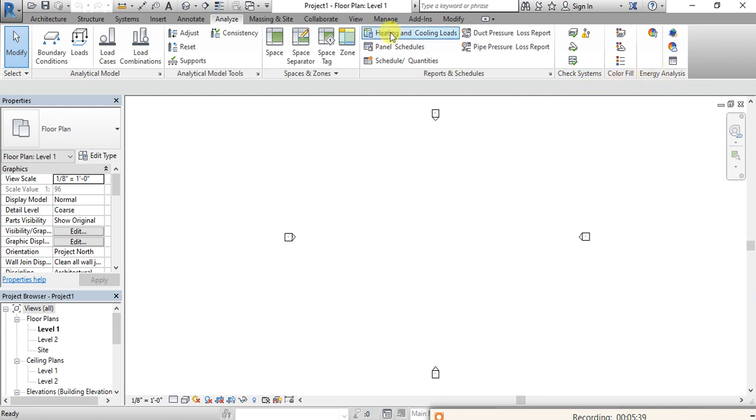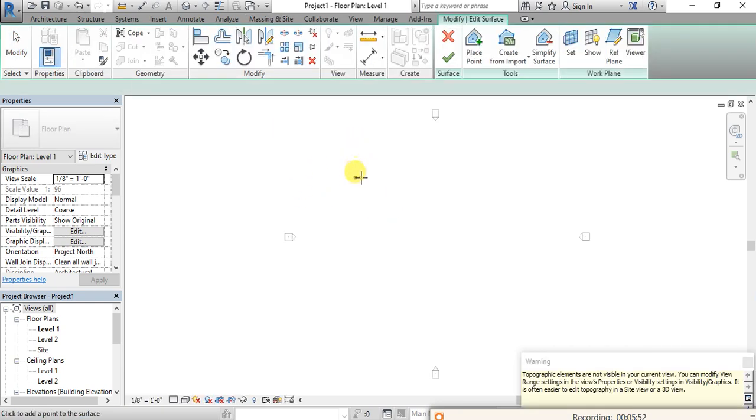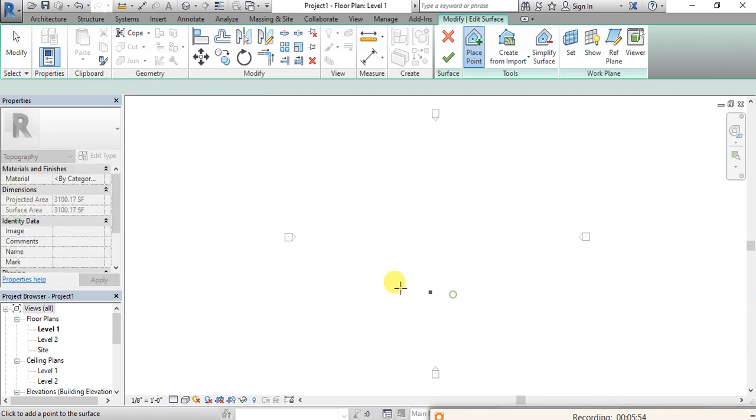project. So if you click on this toposurface, it will give you some options, like clicking on the area. So you will click like this and you will choose the site plan, so it will show to you, and you will click on this finish surface, so a toposurface will be made. I am not using these details now, so these are the different options.